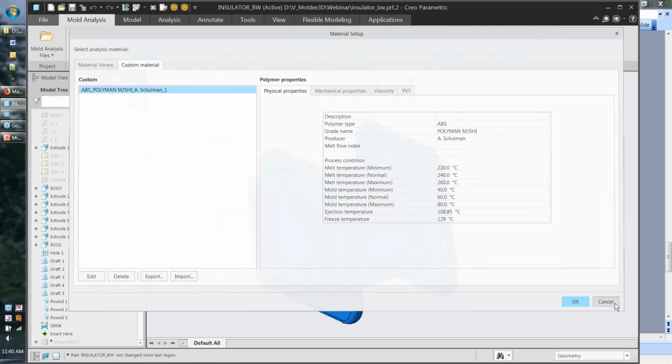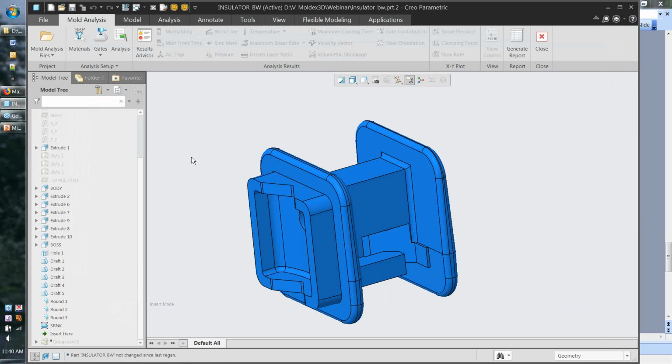You simply search the material library by producer or by family, and I'm very sure that those in the plastic industry are familiar with the meaning thereof. You're either searching by the type of material, to speak to it generically, say polypropylene or nylon, for instance, or you might be searching by material supplier, for example DuPont or A. Schulman. So the material library is very, very deep and very powerful to zoom in on the material that you need to use for your simulation.